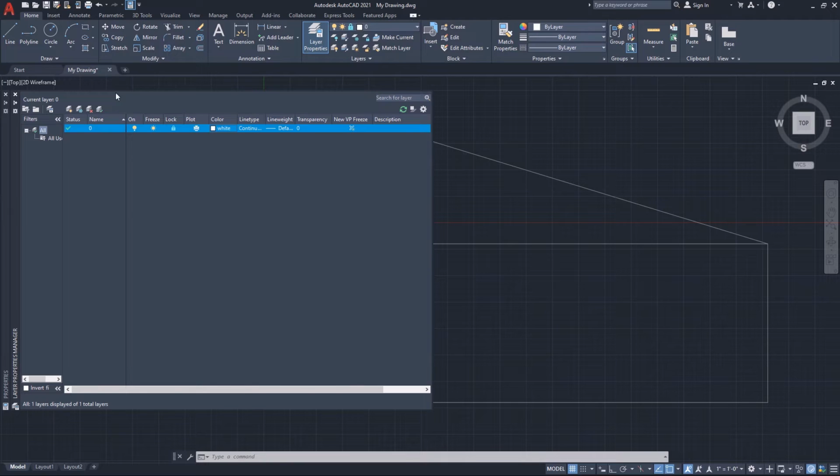The next icon to the right has a red X, and this icon, when selected, activates the ability to delete existing layers. A word of note, existing layers cannot be deleted if there is any object remaining within the drawing file on that layer. The last icon has a green check mark and activates the tool to select an alternative layer to now become the current layer.